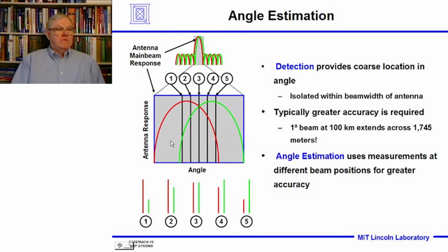And as we move the antenna beam over to the right, you see that the responses get closer and closer together until they're equal when the two antennas are directly aligned with the target. And when they're not aligned, when the yellow one is aligned exactly with the target and the blue beam is not, this would be the response you get from the two antennas.